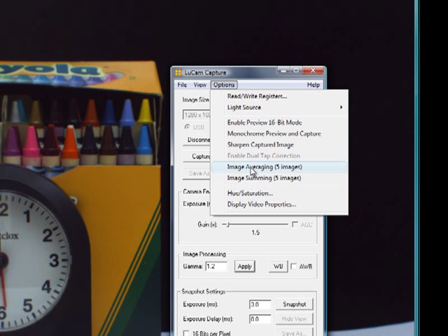Image averaging can be used to help minimize background noise in captured images under higher gain settings. Image summing can be used to add the results from various captured images together. So under dark illuminated conditions where the camera is operating at near maximum exposure time, you can capture multiple frames and sum them together.